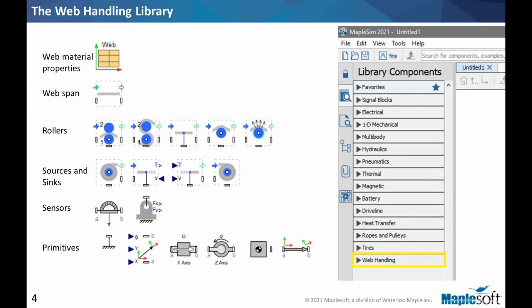And there's a subsection for primitives. This is the library that allows you to move things and place things on the screen, in your actual 2D space. For those who have seen MapleSim, these are borrowed from the multi-body library, but made such that they are simpler and you only have 2D parameters to set. Certainly you can use the multi-body, but just don't use Z. These components make things easier.